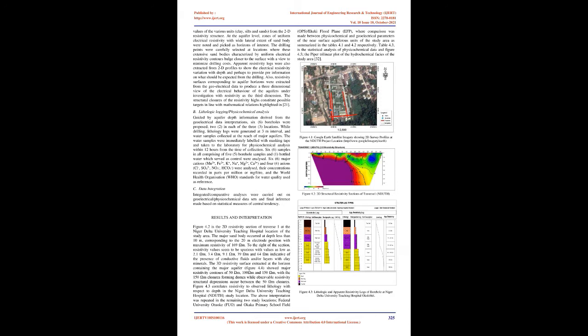The same can be said of similar studies carried out by [2] and [9], to all intent and purpose. The studies integrated geoelectrical, physicochemical, and perhaps acoustic methods to decipher lithology and water content, aquifer. But the aspect of calibrating water quality in a subsurface zone that has been interpreted to be an aquifer with quantitative electrical resistivity range of values, so that water quality can be inferred directly from a resistivity profile with known background geology based on a localized template, is yet to be addressed, and that is the perspective the study seeks to illuminate.